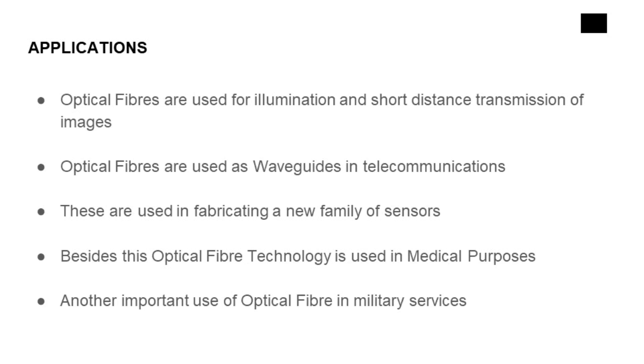For example, a microphone converts sound waves into current. Similarly, a video camera converts images into currents. These electrical signals are of low frequency and cannot be transmitted directly. Therefore, they are superposed on a carrier wave of very high frequency. The process of imposing a message signal on a carrier wave is called modulation. Two different techniques of modulation are available. In analog modulation, a continuous wave carries the message. In digital modulation, the message is transmitted in discrete form using binary digits.